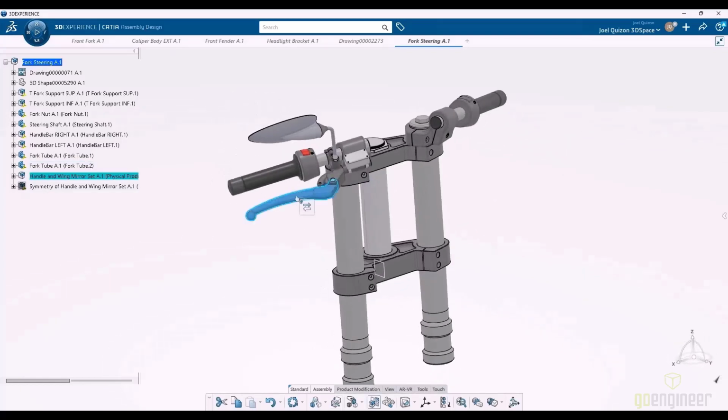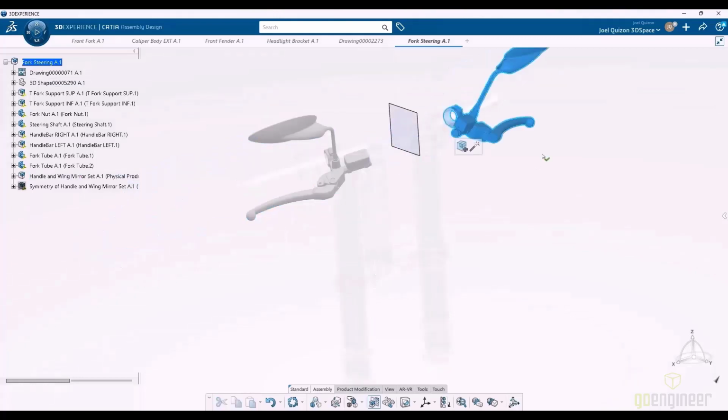When I click on something, here's a great tool. If I hit my shift key, it's basically a selection area where you're able to go in and say, well, I want to select this subassembly, or the full assembly. So it's showing you the different areas or makeup of that component. I'm going to select this big subassembly to mirror, and I'm picking this plane to mirror about.